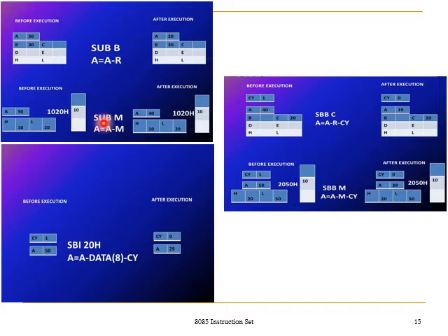If you give SUB M, then the HL register pair content is going to act as a memory location. That memory location data is chosen and the accumulator content is subtracted with the content of the specified memory location. So 50 minus 10, 40, is stored in the accumulator after the execution of this instruction.